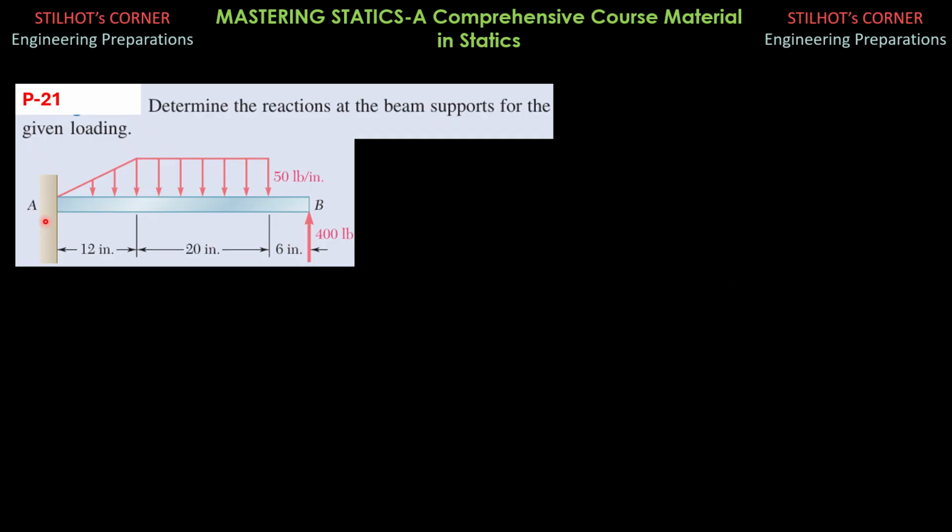So in the free body diagram for the reactions at A, we expect three reactions: horizontal, vertical, and resistance to moment, because this end is fixed as shown here. So these are the reactions. So definitely, summation of forces x is 0. So Ax, the only horizontal force, is 0. So we have an answer. Ax is 0 as first.